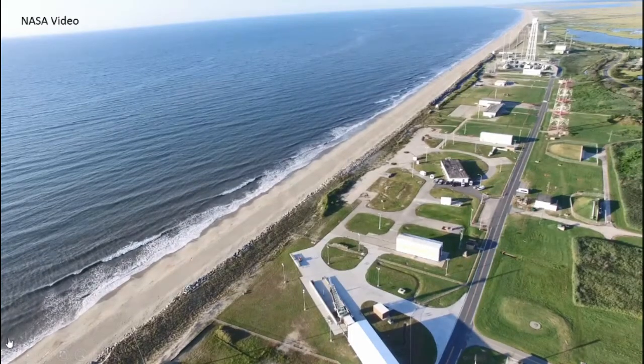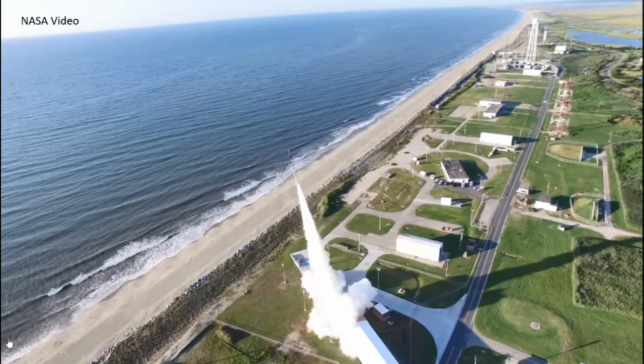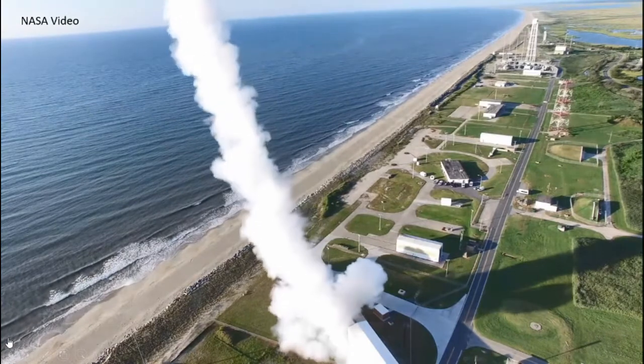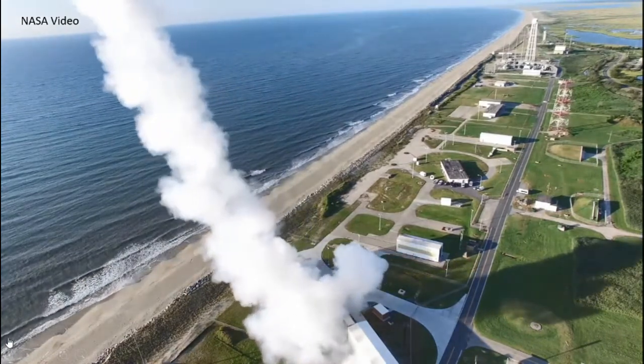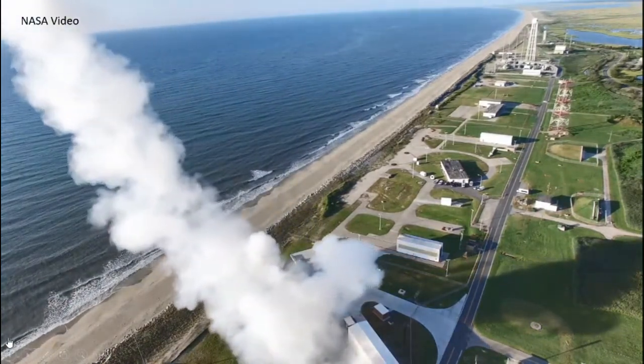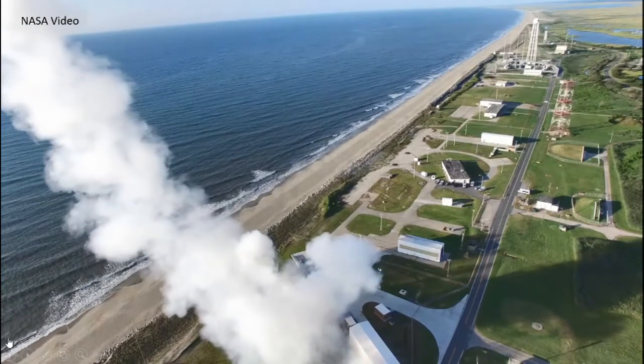First, let's take a look at a sounding rocket launch. Notice how the surface winds blow the rocket exhaust towards the left. Low-level and high-level winds are measured prior to a sounding rocket launch, and the launcher elevation and azimuth are adjusted appropriately to get the rocket to land in the desired impact area.